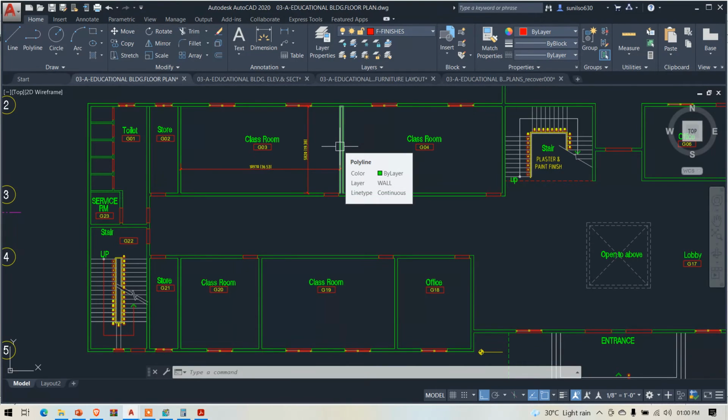So mainly here we have to take only non-AC partitions. We are not going to consider any AC partition. Here I am going to consider only non-AC partition. Since this is the classroom, here also we are providing AC, so from this partition we won't get any heat. So this partition we call an AC partition, meaning 0 heat generation.